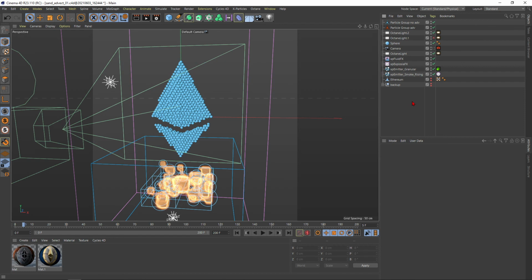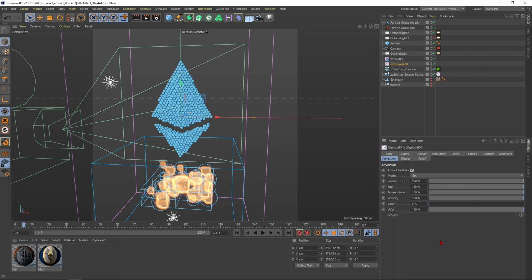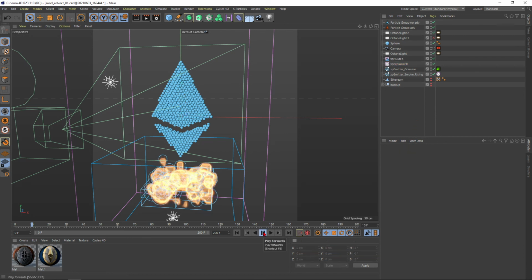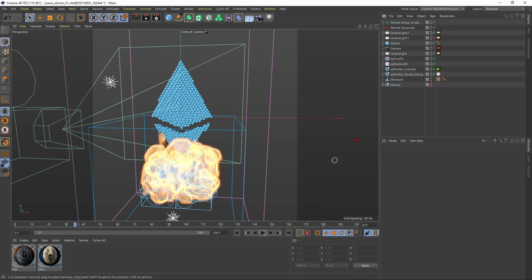All right, now they are in this basic group. Okay, and we want to dynamically change them to another group, and only these particles will be advected by the fire. We go to our exposure effects, go to advection, and now we can say which group will be advected. Then we just place the group advected in it, and that just means all particles in this group will be advected. All right, obviously now none of these particles will be advected. That's pretty sad.